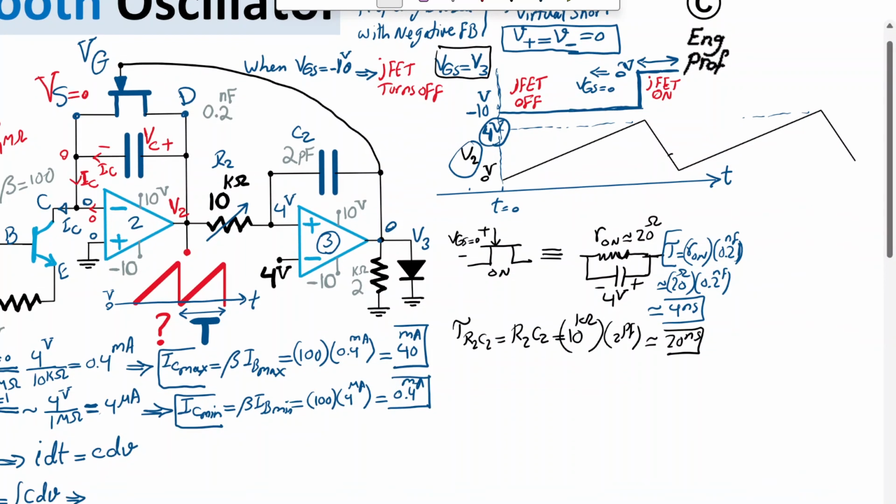Okay, so now the remaining portion is I need to compute this time. What is it? Because I already computed this time, which is practically very small. So this time, if I refer to it, I can say it's effectively 4 times tau that I computed here. So this time effectively is about, say, 16 nanosecond.